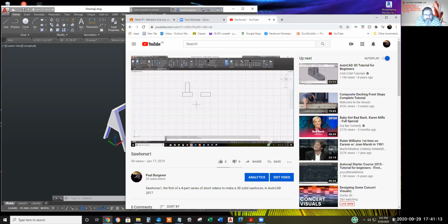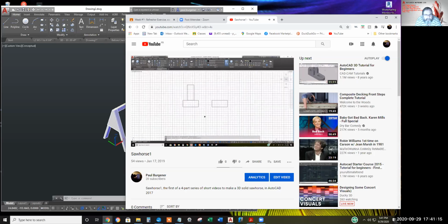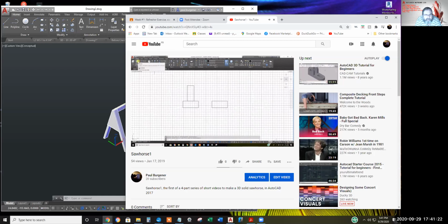I don't think I've extruded yet. Start three here. Three rectangles. Let's extrude. On the home tab, the 3D modeling workspace drop down. Go three at once. Hit enter. You can also hit enter by right click and select enter. Enter. 48 inches long.